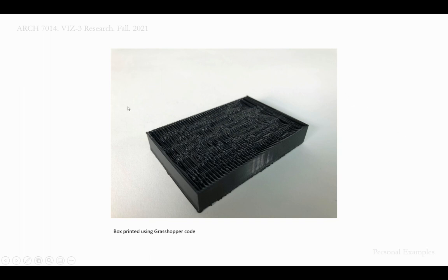So then, it's not the exact box that I showed, but this begins to show things that you can create when you begin to manipulate your G-code. So here, I just have a regular box on the outside, but then I manipulated the points on the top to get this wavy pattern. So I've actually manipulated the G-code in such a way that the material doesn't touch, and it just creates this thin spaghetti over the top.